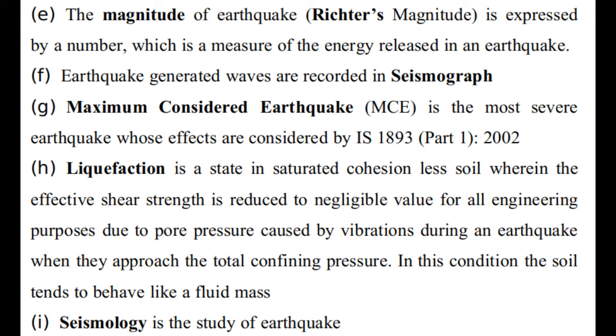But why does liquefaction happen? This is due to the pore pressure caused by the vibrations during an earthquake when they approach the total confining pressure. In this condition, the soil tends to behave like a fluid mass. Okay. Next is seismology. What is seismology? Seismology is the study of the earthquake.